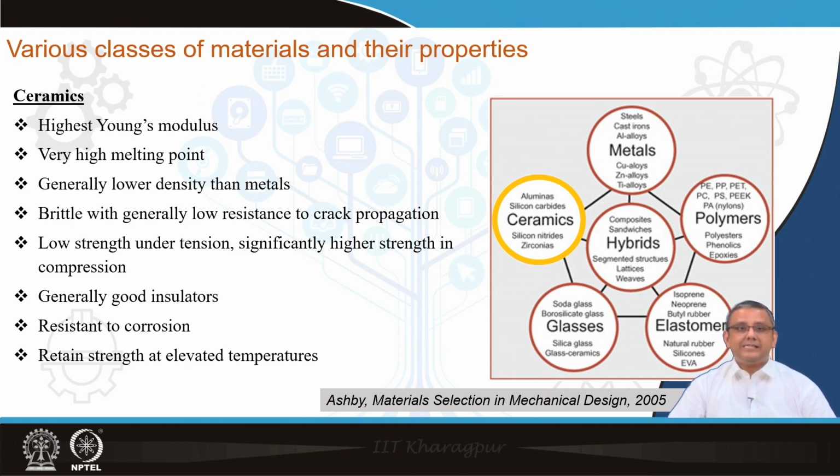Because ceramics possess extremely low fracture toughness, and even a small crack can propagate in a catastrophic manner, ceramics are very poor in tensile loading. That means, if a ceramic sample is loaded under tension, it almost always breaks soon after the test starts. But if the same sample is loaded under compression, the crack is not opening, it is closing,